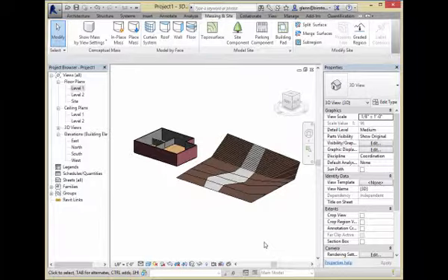Okay, next up, cropping in 3D. Let's talk about this. This is actually a fun one. Okay, 2 different big things going on, cropping versus the 3D section box. The 3D section box is a fantastic way of just kind of cutting through things. Every view can have a section box. The default 3D view, any of your 3D views can.